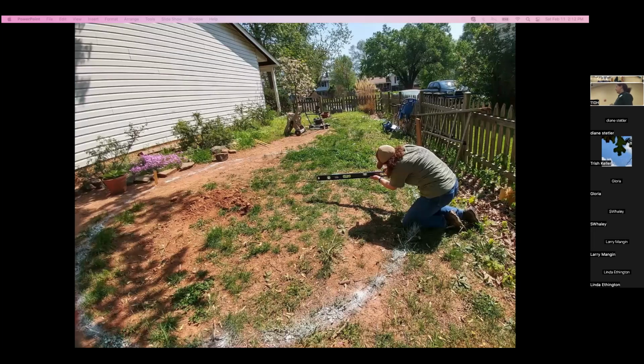All right, and now some actual pictures. So this is a rain garden that we did for a homeowner in Manassas. You can see we sprayed painted the perimeter of that rain garden. That's me. We have the upslope stake and the downslope stake already in, and we have a rope tied between the two stakes. And I'm just making sure that rope is level as we're constructing our rain garden to make sure we meet all the dimensions we got from our calculation.